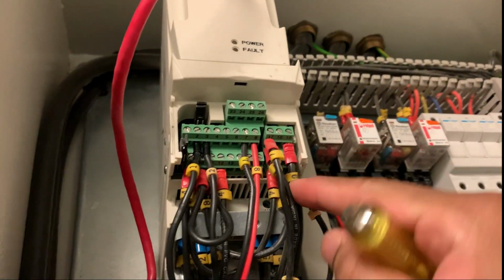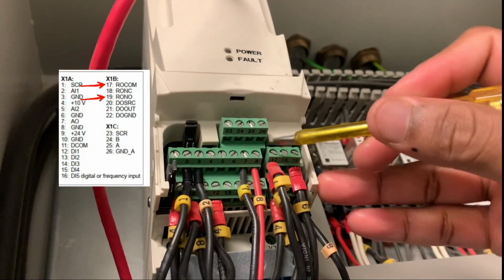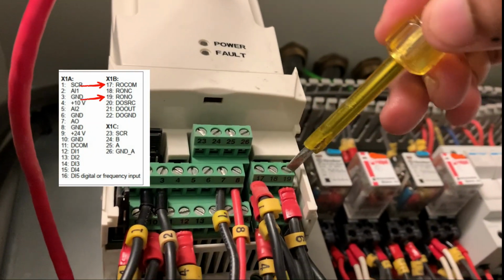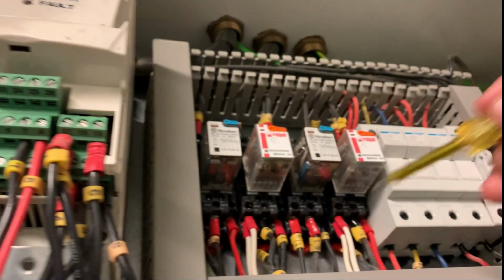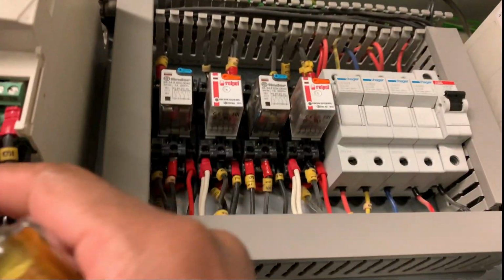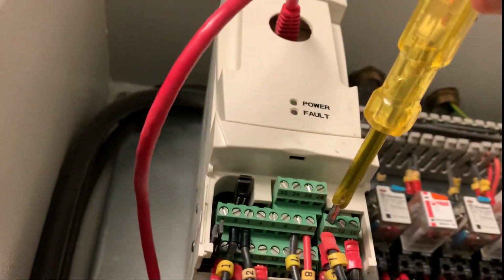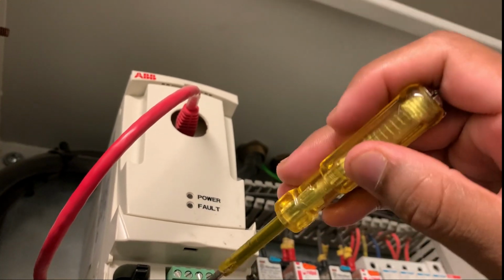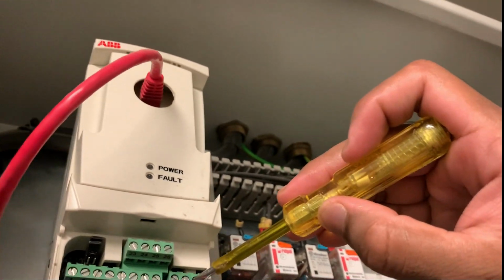Okay, this is the relay. As you can see, in this relay there is a cable connected to terminals 17 and 19. When this relay gets actuated, it will trigger this other relay. Let me show you the relay. As you can see, in 17 we have a phase. If it's visible or not, I don't know, but there is a current over here. So when the motor runs and this relay gets actuated, it will transfer this phase to the 19 terminal.